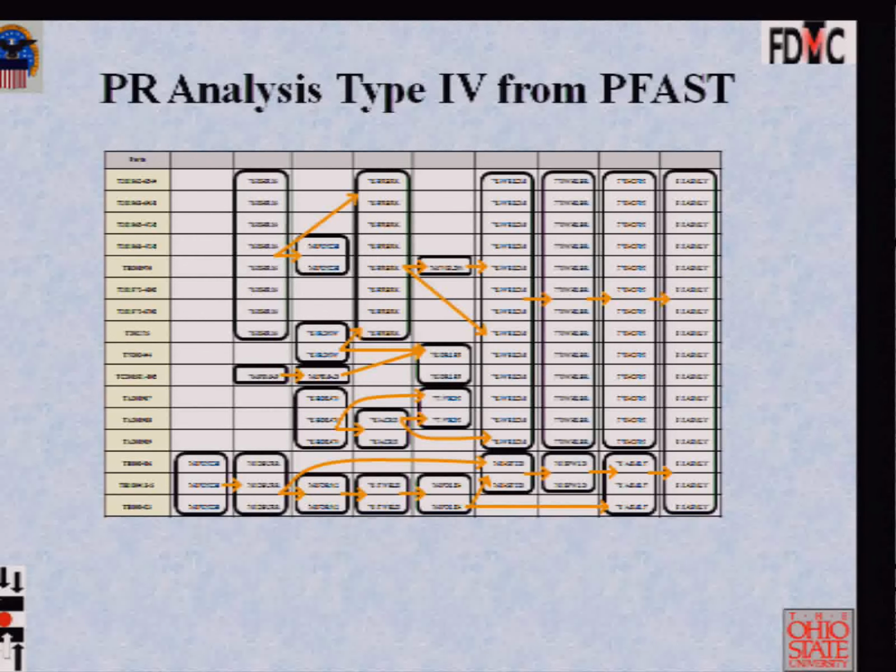Look at your bill of materials, look at the operations process chart, look at the logical sub-assembly points. Whichever work centers are creating these sub-assemblies, that's where you want to put these supermarkets. And by color coding and labeling, or having different racks or different areas for storage of individual kits of parts, you know where to put the supermarkets, right where components become sub-assemblies and sub-assemblies become larger sub-assemblies or the final